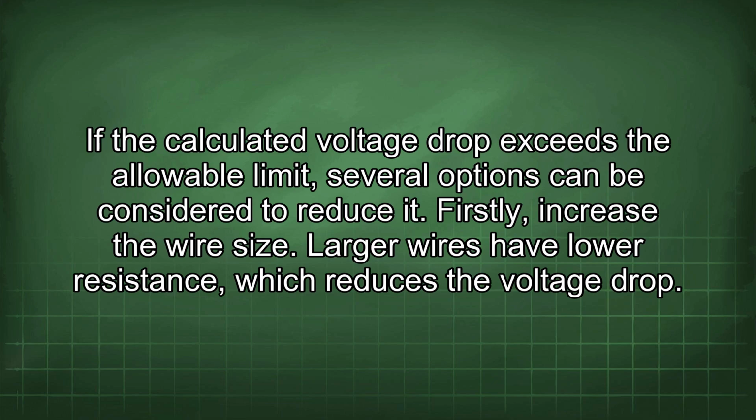If the calculated voltage drop exceeds the allowable limit, several options can be considered to reduce it. Firstly, increase the wire size. Larger wires have lower resistance, which reduces the voltage drop.